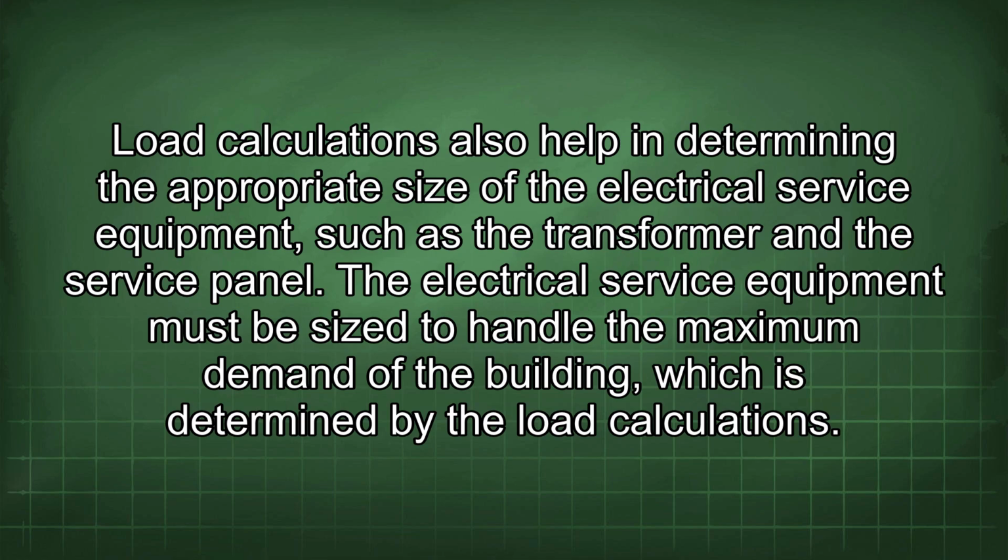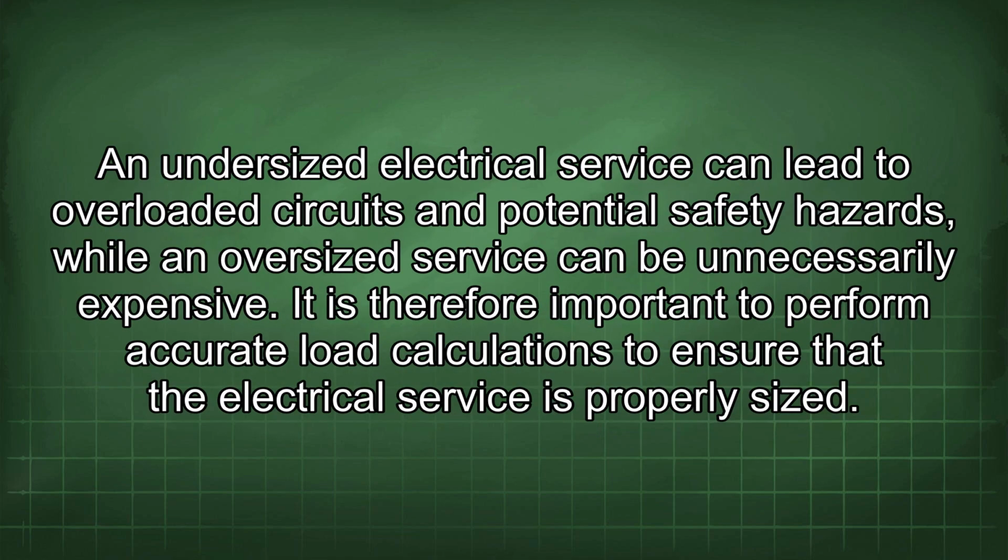Load calculations also help in determining the appropriate size of the electrical service equipment, such as the transformer and the service panel. The electrical service equipment must be sized to handle the maximum demand of the building, which is determined by the load calculations. An undersized electrical service can lead to overloaded circuits and potential safety hazards, while an oversized service can be unnecessarily expensive. It is therefore important to perform accurate load calculations to ensure that the electrical service is properly sized.